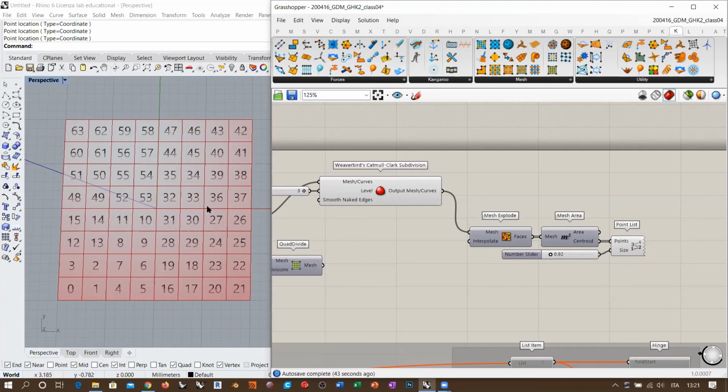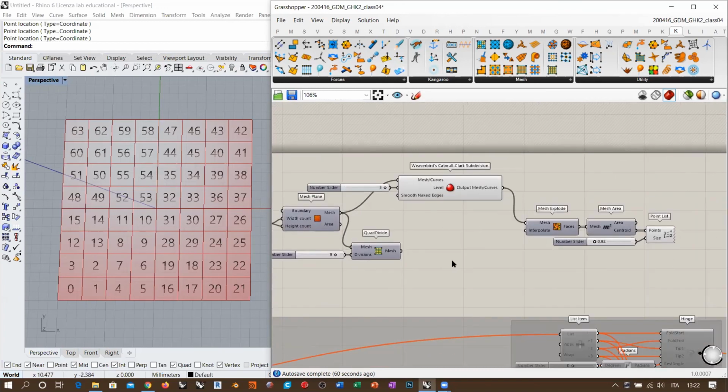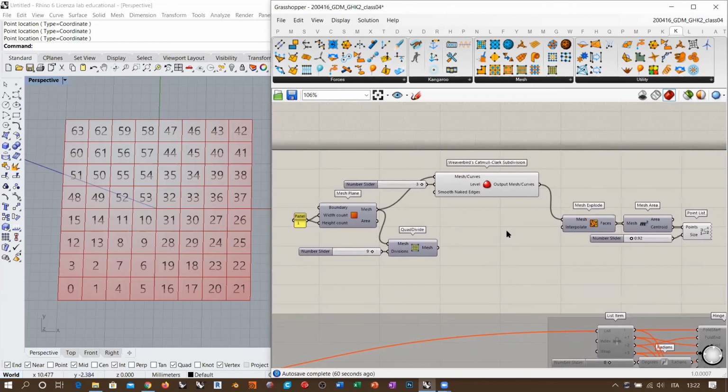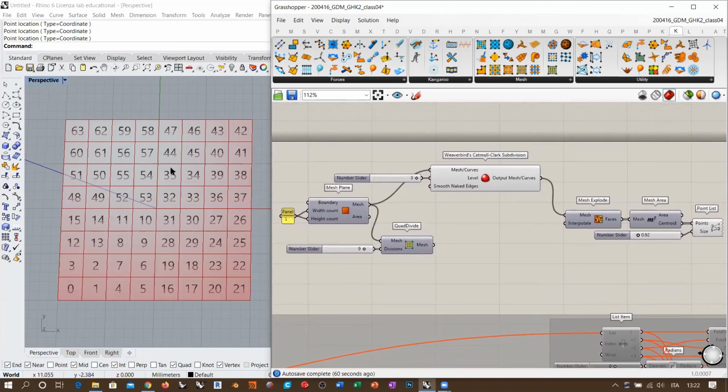So it's a totally chaotic set of polygons. Well, not that chaotic, it is understandable, but it's very difficult to operate on this mesh once you have applied the Catmull-Clark subdivision. So yes, subdivision affects the workflow because it can mess things up in a very weird way that makes it very difficult to reconstruct, for example, say you want diagonals.